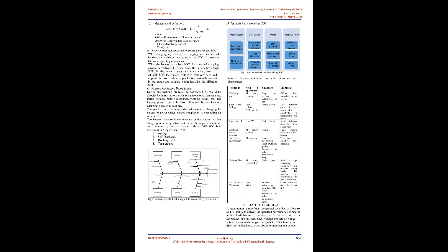3. State of charge, SOC. Precise knowledge of SOC exerts additional control over the charging and discharging processes, which is employed to increase battery life. A. SOC definitions. 1. General definition: ratio of the available capacity to the rated capacity. 2. Physical definition: ratio of remaining active material to the total active material inside the battery that can be converted into electrical energy from chemical energy. 3. Mathematical definition.